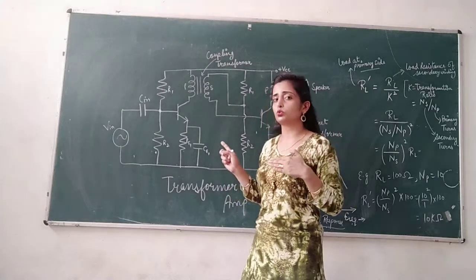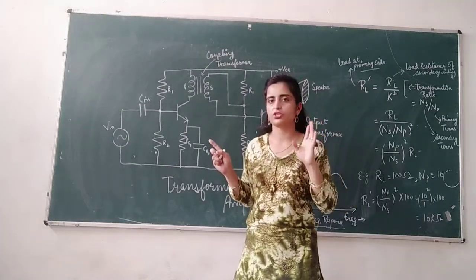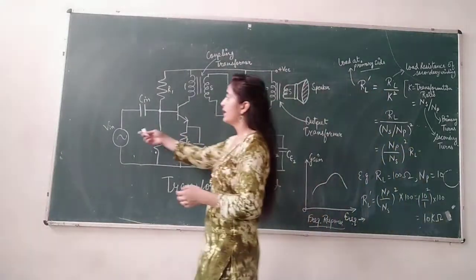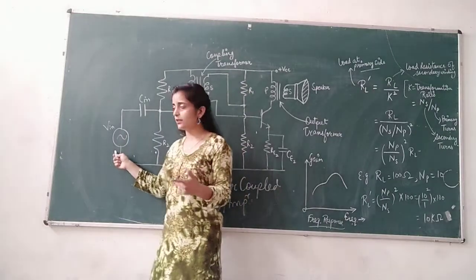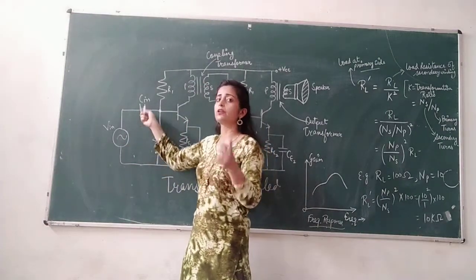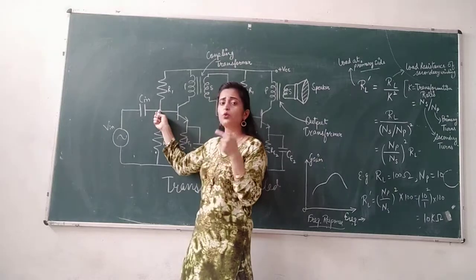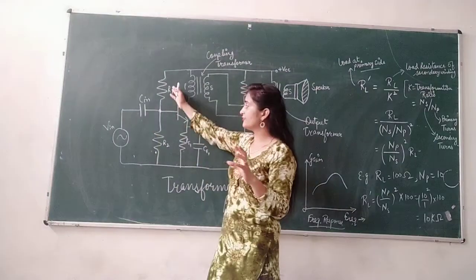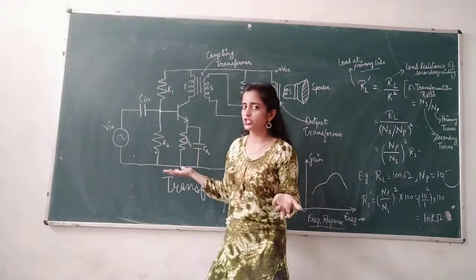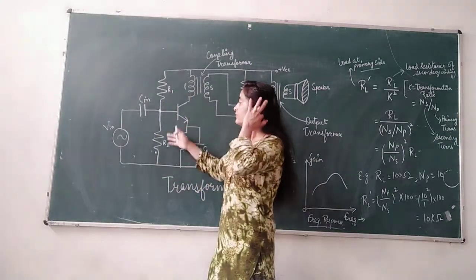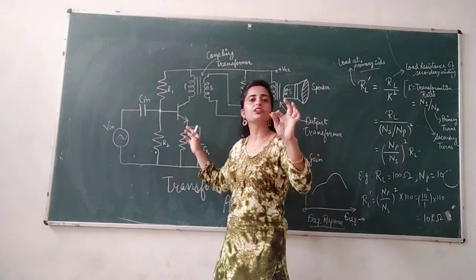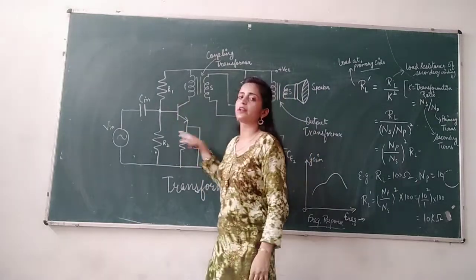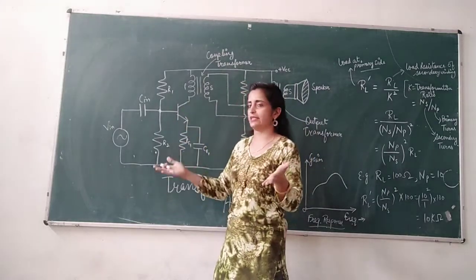as per the rules. That is, first of all, there will be construction. In the construction of this transformer coupled amplifier, at first we have the input AC signal, then the capacitor Cin for passing only the desired AC signals from this input signal, then R1 and R2 working as a potential divider biasing circuit, so that the operating point of the transistor remains constant, and that helps the transistor to amplify the signal, right?